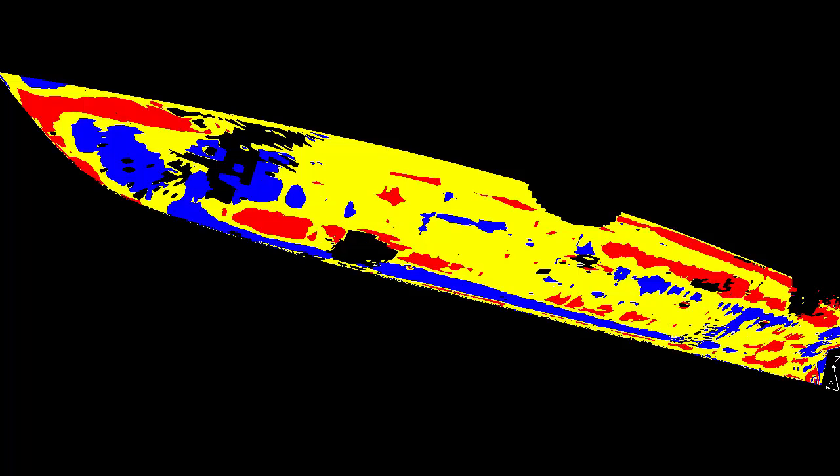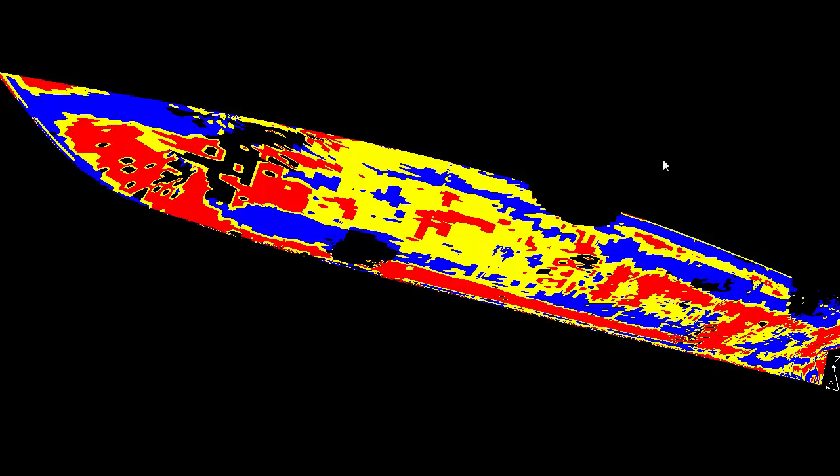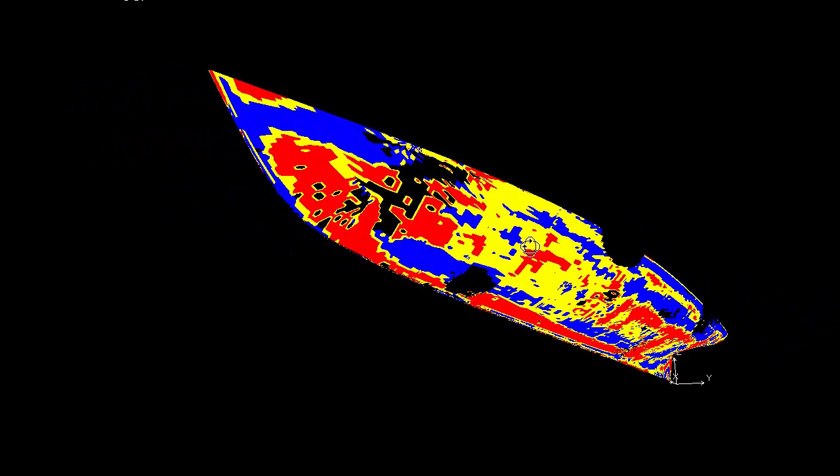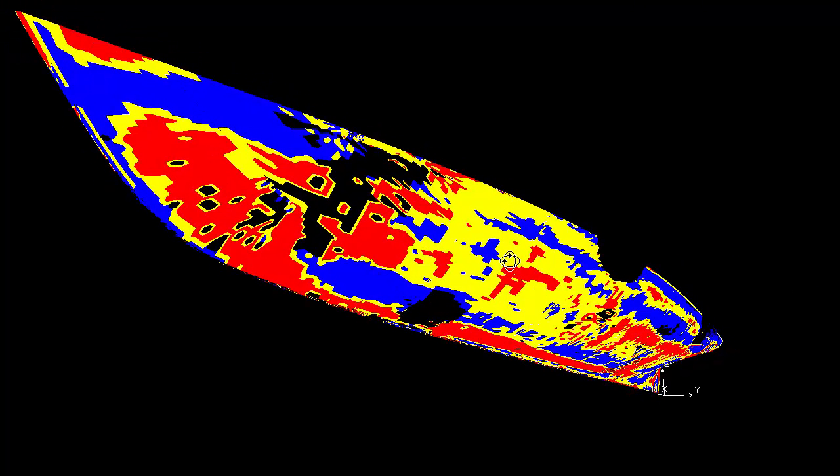We can also look at the areas of the surface that are within the thickness of the cloud in terms of the min and max normal distances. So you can see, now we can start to see how well we're doing with the metrics of the data itself. So we get quite a lot of feedback, and these are a useful set of tools to present to other people that might not be working on the project, present to the customer, highlight directly how accurate you're getting your surface.